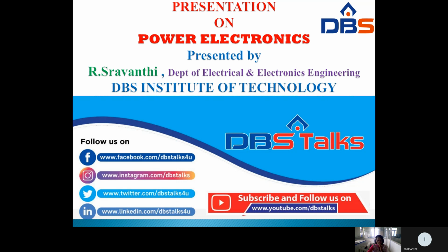The capacitor C charges up with the dot as positive before a positive pulse is applied to the SCR. When the SCR is triggered, the resulting current has two components. The constant load current I load flows through the R load. This is ensured by the large reactance in series with the load and the freewheeling diode clamping it. A sinusoidal current flows through the resonant LC circuit to charge up the capacitor with the dot as